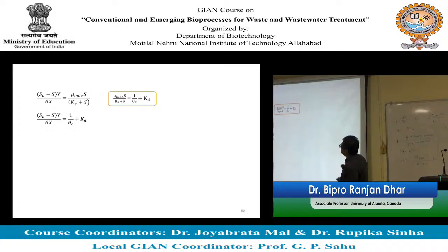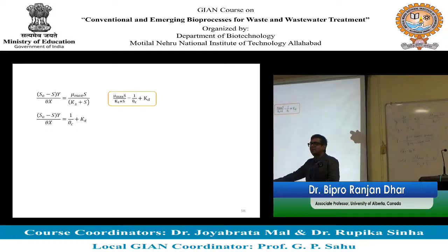My initial BOD, I am going to know what my characteristics are. Final BOD is my target, what I want to achieve. So what is left in this equation is theta, theta c and X. So SRT, HRT and biomass, right? That means if my other stuff is fixed, I can basically manipulate SRT and HRT and I can maintain a certain biomass concentration.